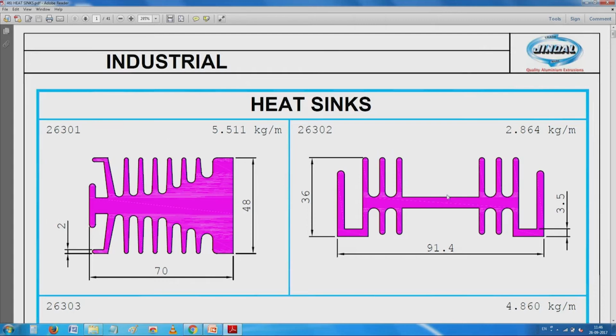If you take this right side one, mount a small device here, you will see that towards the end it has become very cold, and if you go to the fin tip, you will notice that not much temperature differential exists between the tip and the ambient. As such, it will not be able to maintain the heat transfer rate which we are looking for.